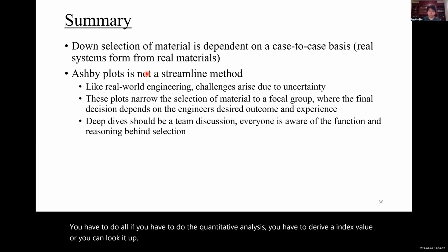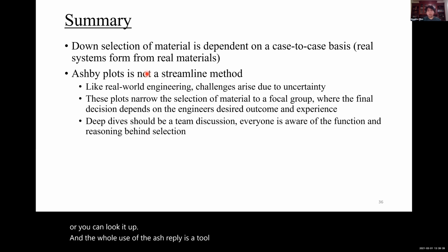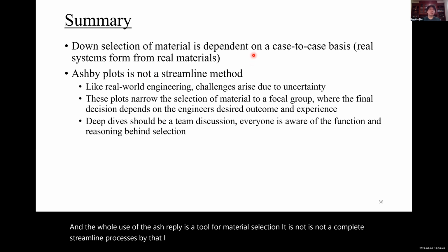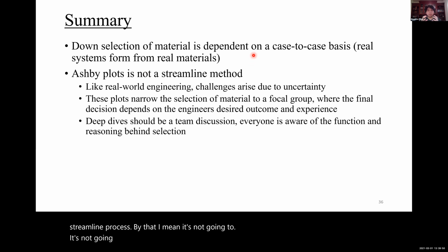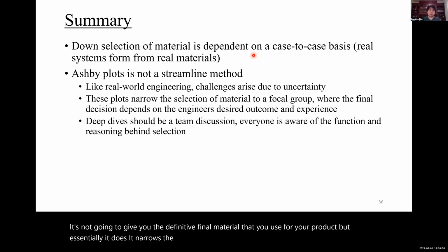The whole use of the Ashby plot as a tool for material selection is not a complete streamlined process. By that I mean it's not going to give you the definitive final material that you use for your product. What it essentially does is narrow the selection into a focal group, and you have to decide, along with your team and your customer, which material best suits your need.